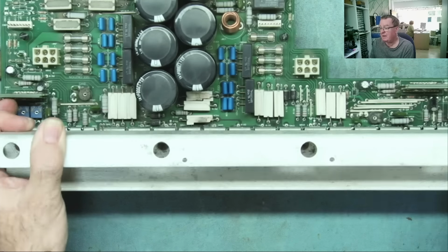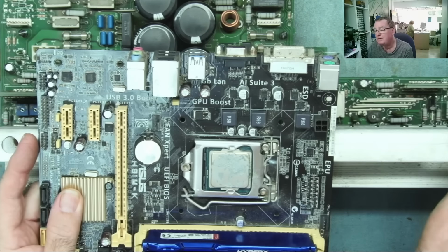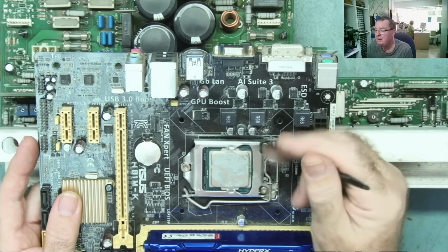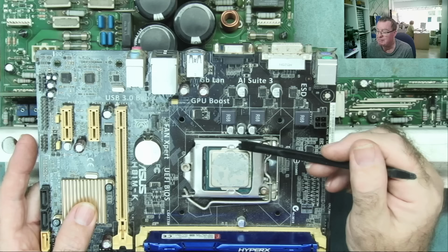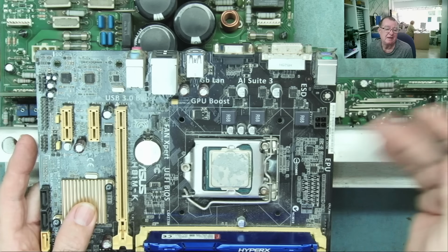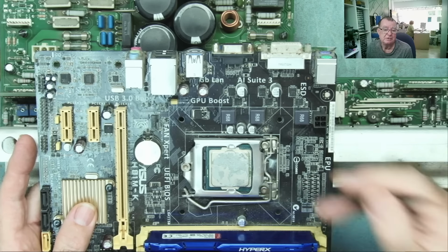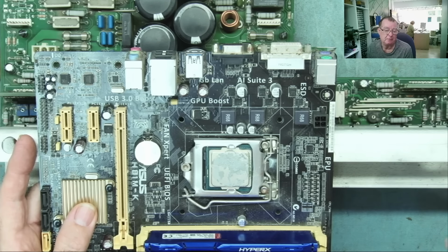Another reason, as I just mentioned, could be bad design. If you have the most powerful or power hungry processor for that platform, you may be pushing these, which are powering it, to the limit. And in that case, they may just fail, okay? Yes, we can have abuse, such as a short circuit CPU. That may well cause them to fail.